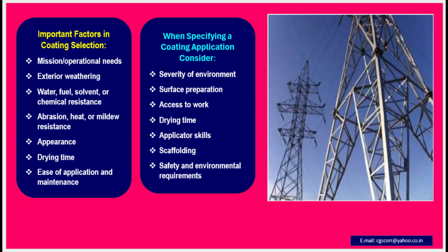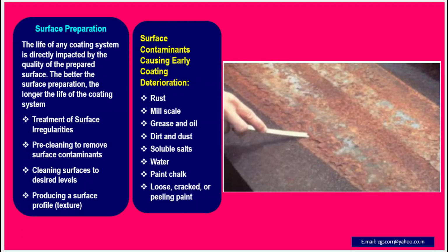When specifying a coating application, consider the following factors. The topmost is severity of the environment, surface preparation, access to work, drying time, applicator skills, scaffolding, safety and environmental requirements.